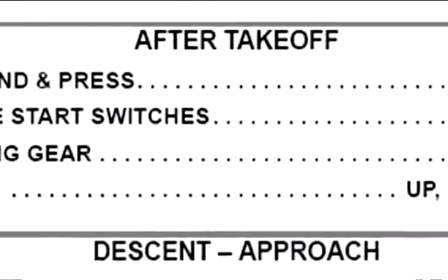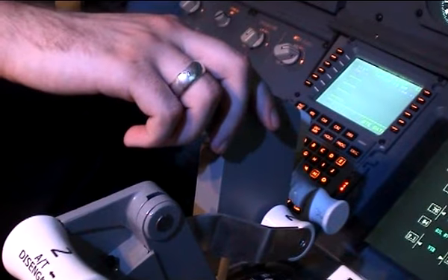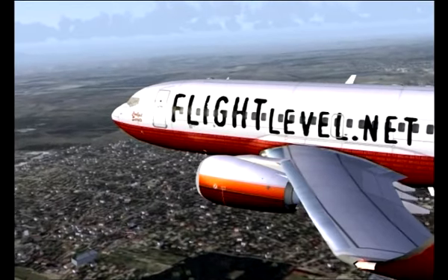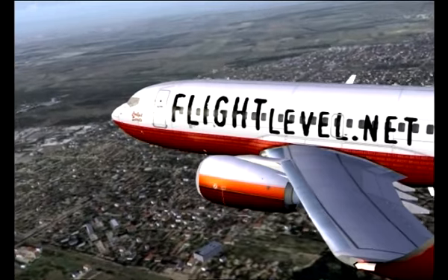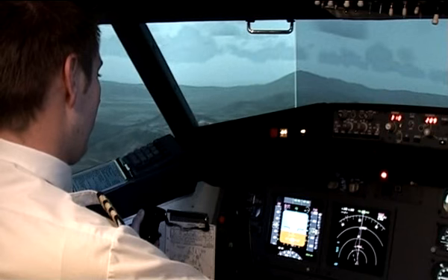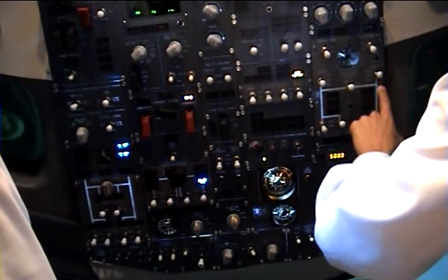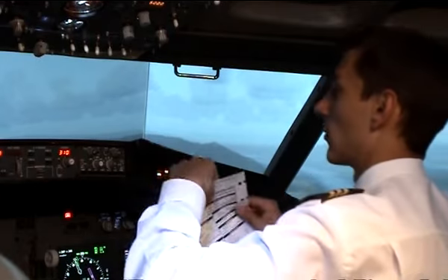In an emergency, it's crucial to use checklists for each phase of the flight. Pilots that are too nervous or tense while following emergency procedures might easily forget to complete some routine tasks. Okay, standing by for the checklist. After takeoff checklist. After takeoff checklist, please. Engine bleeds both sides on. Packs, left auto, right pack off. Landing gear up and off. Flaps up, no lights. After takeoff checklist completed.